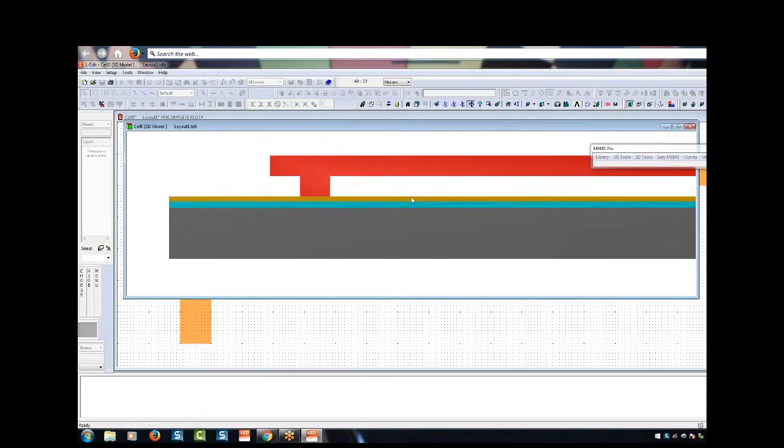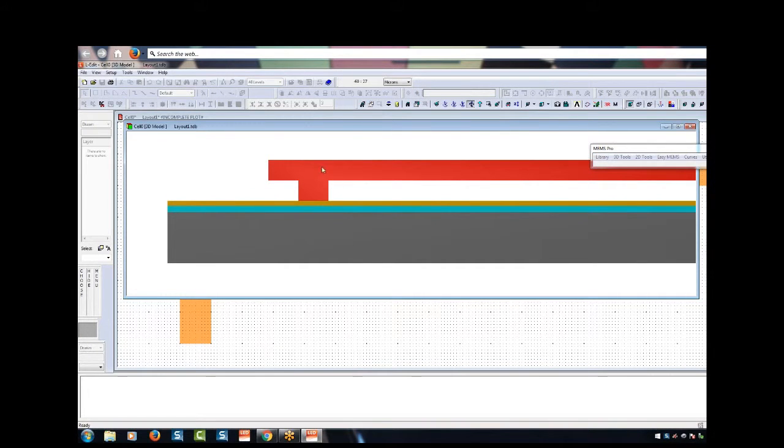up and down. Okay? So you can see, here's your substrate. This is your crystalline silicon wafer, the gray stuff. The blue stuff here is silicon nitride, typically. And you can look at the PolyMUMPS process and design manual, and it'll tell you what the order of these are. And this is your Poly 0.